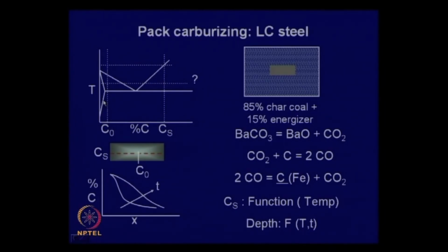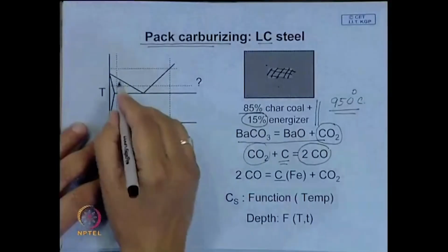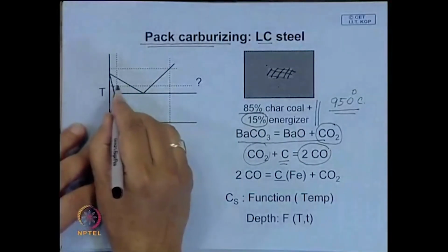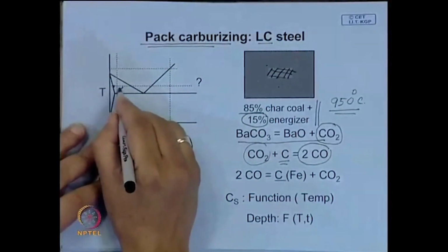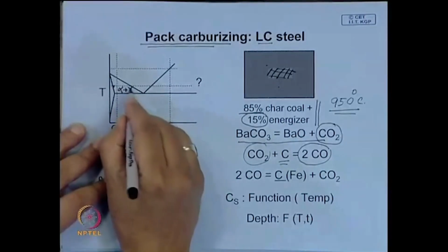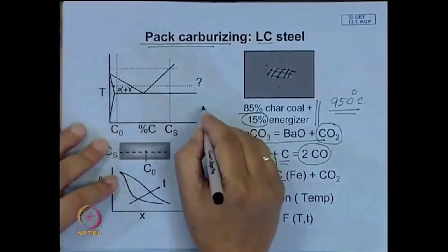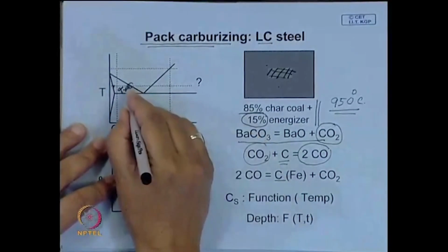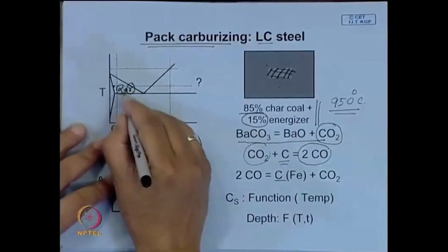So, this ferrite is saturated, so it cannot absorb much carbon. Now the question is, can you do a carburization over here? But the problem is, if you heat here, it will be a two phase structure. At this temperature, the structure is made up of ferrite plus austenite. Yes, of course, austenite can dissolve a high amount of carbon, but not ferrite.